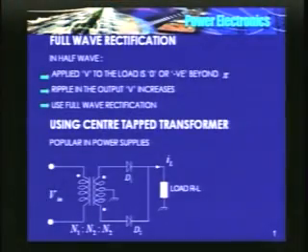Hello. In the last class, we discussed half wave uncontrolled rectification. What are our observations? There was one diode in between the source and the load. We found that as the load inductance increases, the duration for which the diode conducts also increases. But then the voltage applied to the load becomes negative. Therefore, the rate at which the current decays also increases.